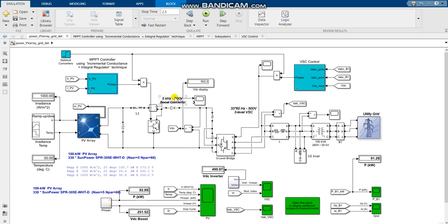Now, the semiconductor devices that this boost converter uses are an IGBT for the switch, as well as a diode. One peculiar thing about these is that they were programmed to not have any forward voltage drop. Realistically, there would be some sort of voltage drop due to these components. If they were silicon, it'd be around 0.7 volts.